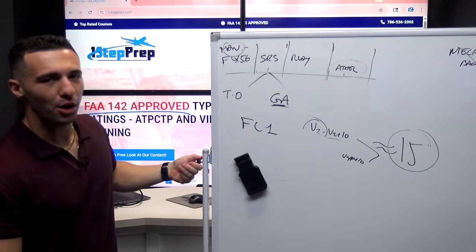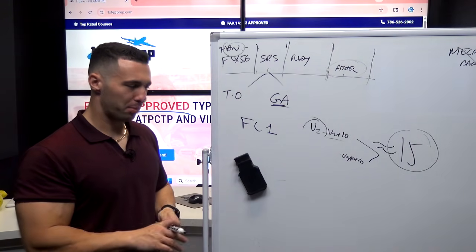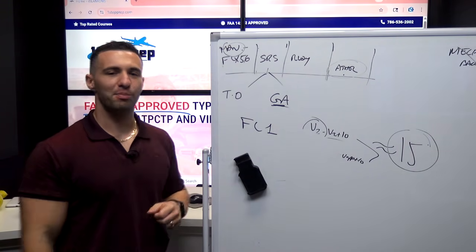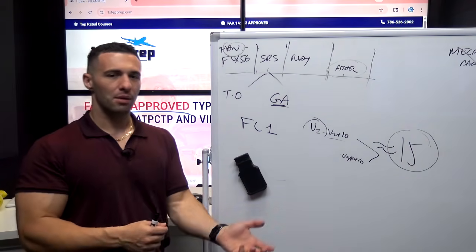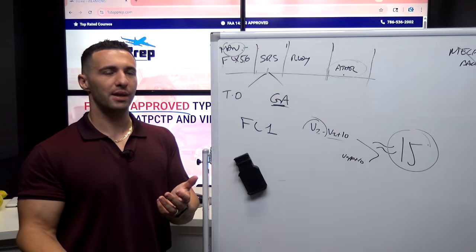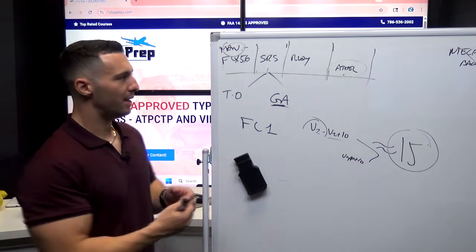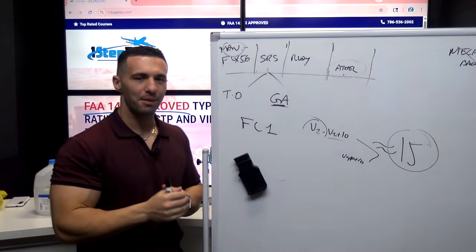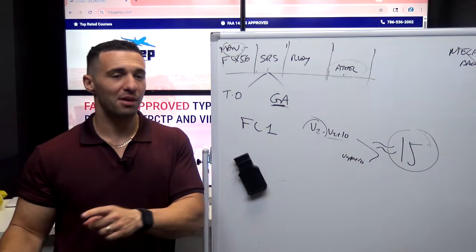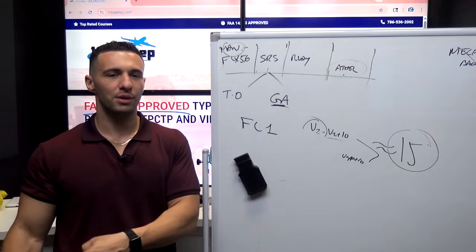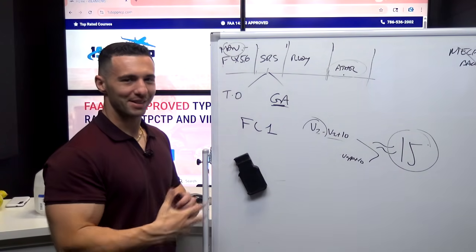This is why, in the no slat, no flap approach and landing that we do in the sim, the status page, when we get to status, is status, right? Stop ECAM, checklist relay reset. No, okay, continue ECAM. And then it basically says set configuration 1 for landing, and it's like, yeah, but I don't have any flaps, so why do I put them in 1? Because the only way to get SRS on a go around is to have flap 1. I got to be able to hit TOGA and have the flaps out. So it's really a matter of, you're actually not having the flaps out, you're having the flap handle. It's looking at the flap handle. I got to have them out so that the computer recognizes that SRS is prudent given the configuration that we're in.